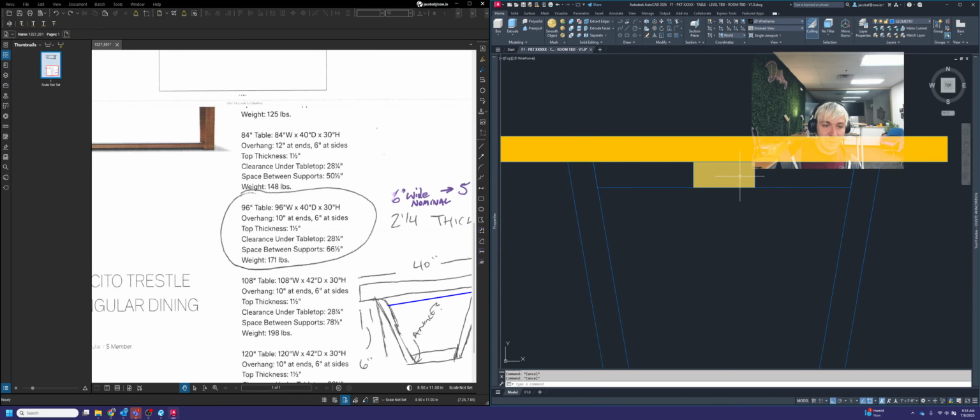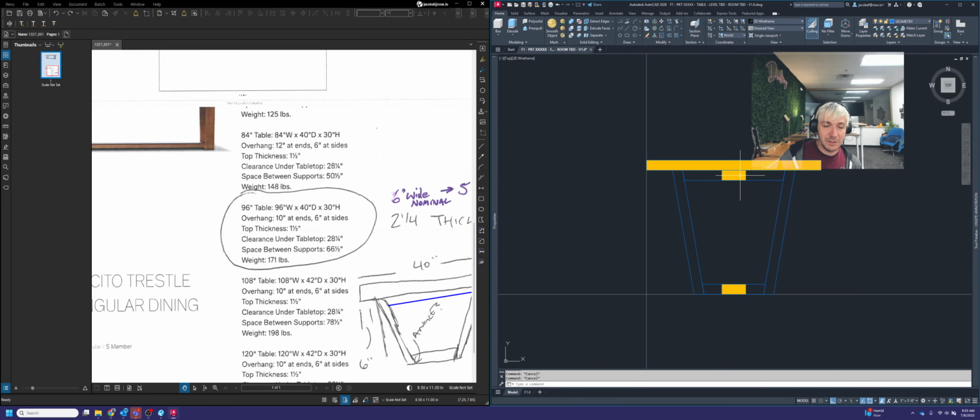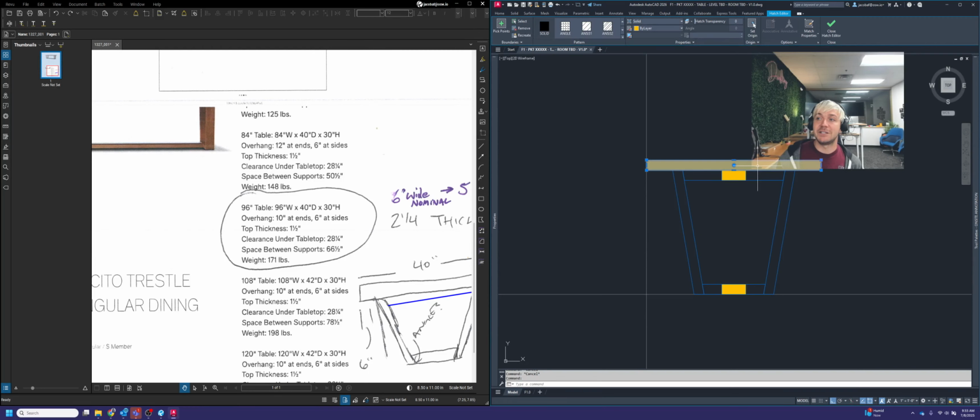One last thing to worry about here in your section view are these solid boxes. These are going to be the intersection fill or the hatching. So what you want to do is change these out. If you click on these hatch boxes, you can go up to your hatch toolbar at the top.